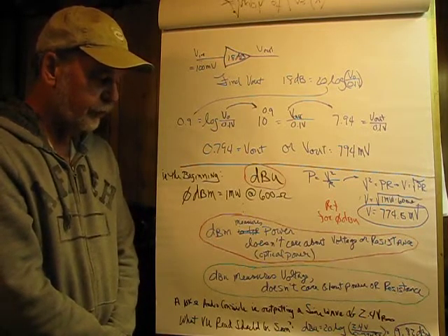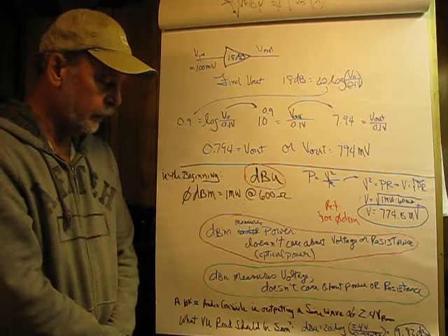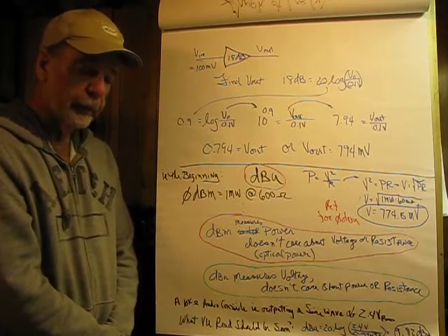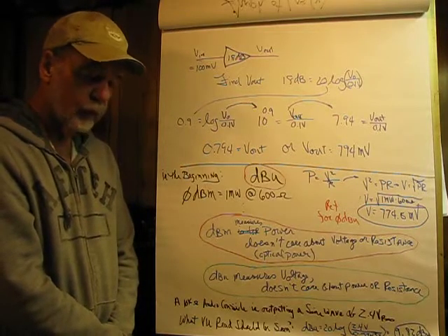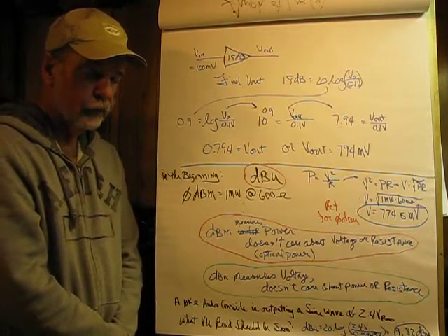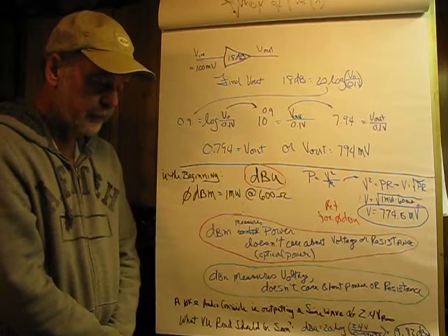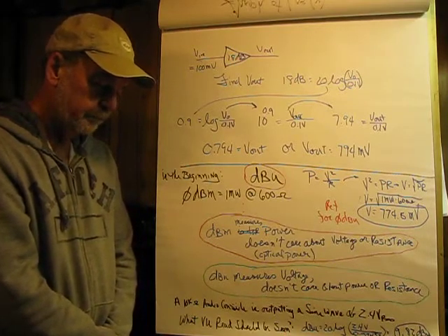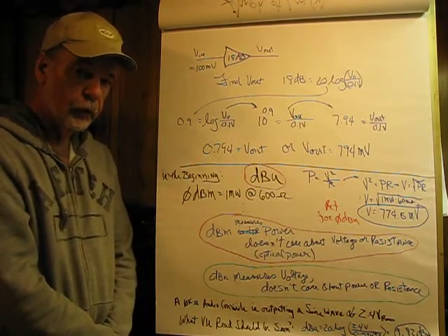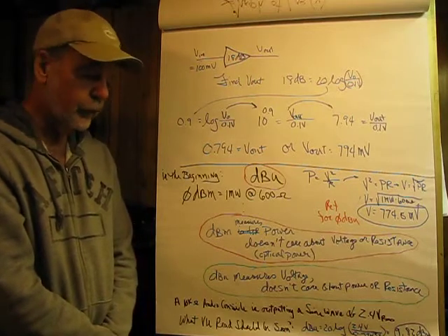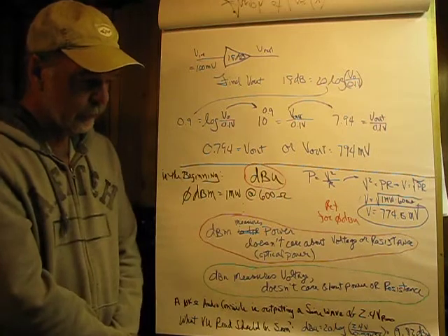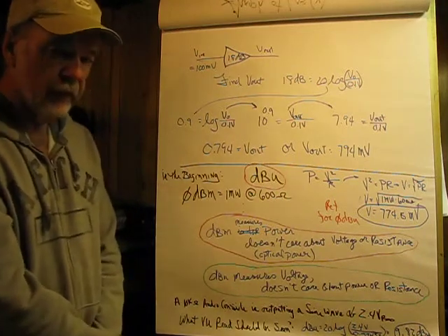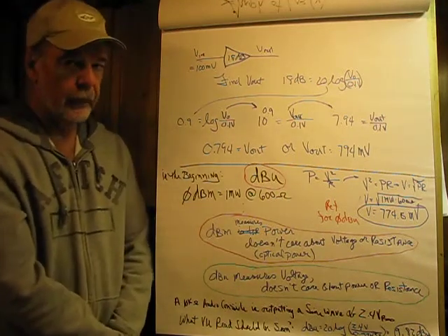So we have basically 4 different references that we're going to be using. dBm would be 1 milliwatt. Multisim uses 1 volt peak for a reference. Our scopes in FFT mode use 1 volt RMS for a reference, and if you're involved in audio, it's 774.5 millivolts for a reference.